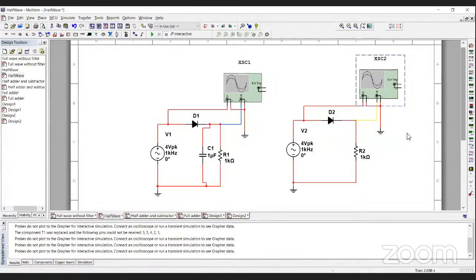Of course, the values are very important. That is what you have to use in your calculation. For example, if you are designing a low pass filter and you want 1 kilohertz as the cutoff frequency, what will be the component list? You'll either choose your resistor or capacitor as fixed, and then change the other value, because frequency is equal to 1 by 2 pi of the component. So here also you'll have calculations and values which you can observe.